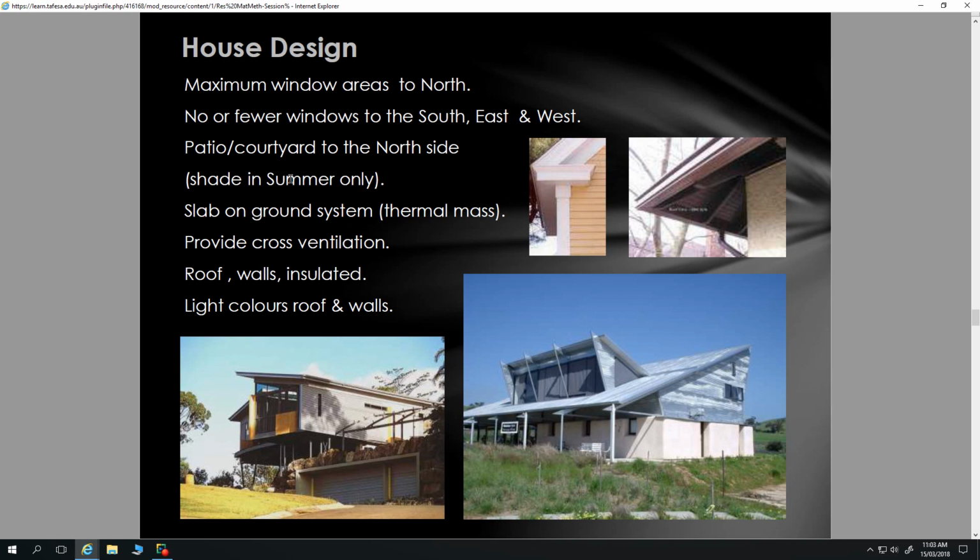Thermal mass can certainly be a curse. I live in a very old cottage with walls about this wide. If we get a really long hot spell, after that you can't cool it down. The building just stays hot, and that's where thermal mass can be a curse. And likewise to warm it up, it takes decent input.